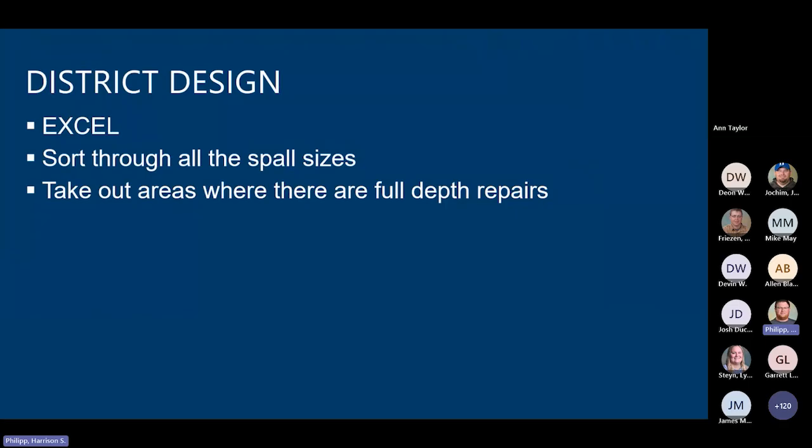There's a lot of time spent on the software to mark out the cracks and spalls, but you're able to do this during the winter months and not have 2 to 4 people on the job site during the summer months. After you're done with the software, another person or the same person has to go through the Excel and sort through all the spalls. This was our first time doing it, so we had a lot of small spalls to sort out. Also, the roadway was pretty bad, so the Excel list was pretty long for 2 lanes on interstate.